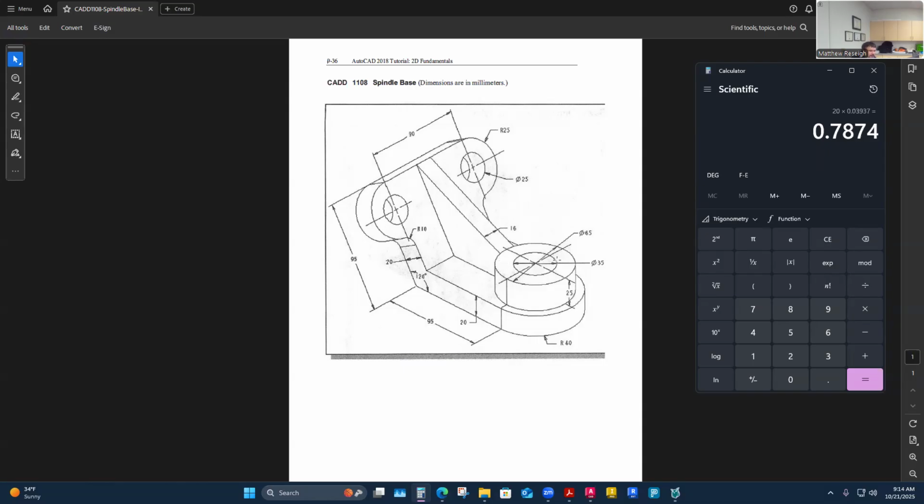What I have is a cylindrical feature. Maybe this is a piece of pipe placed on this plate that's been bent with holes in it. Maybe this was cut out when it was flat and then bent to be L-shaped. And then I have this little gusset support here. When you see something like this, generally it's a rigidizing feature. This part might be experiencing some kind of load between whatever these holes are mounting to and whatever's going through here. They're just worried about the bent nature of this.